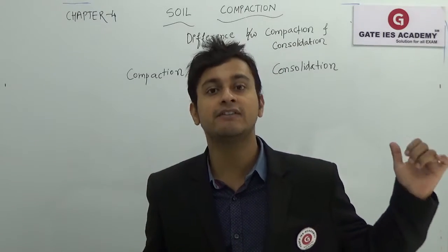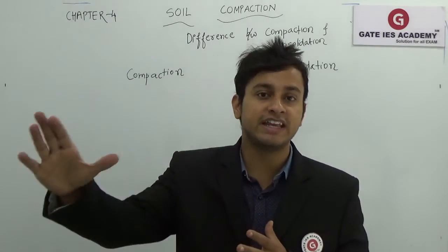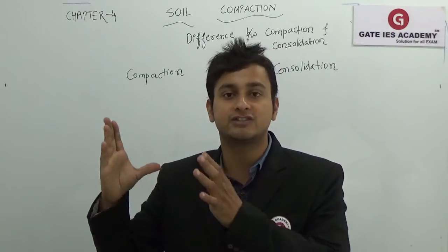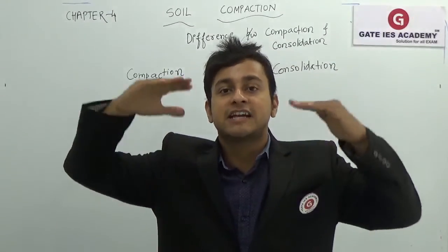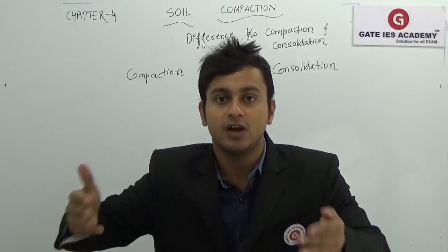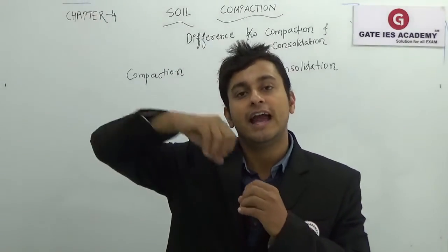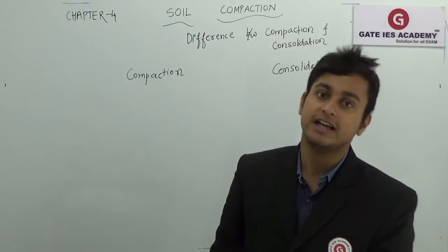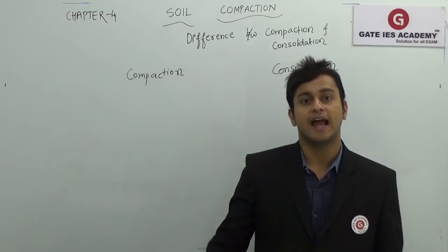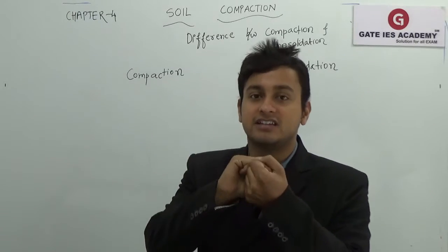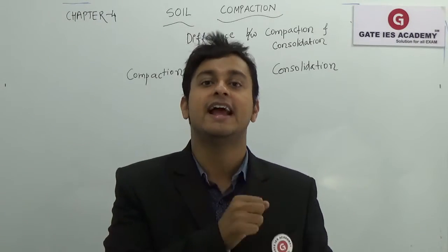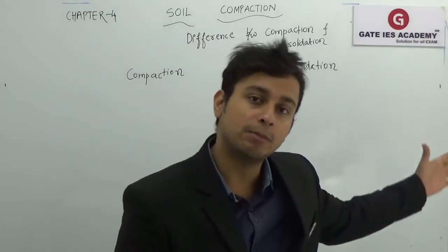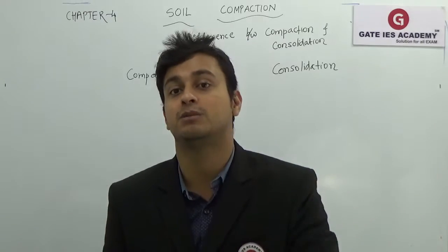Here in compaction we have unsaturated soil. So we don't have any air voids in consolidation. It is a fully saturated soil, and under direct loading which is kept for a long duration of time, the water expels out of the system. That is nothing but the excess pore water pressure that is coming out of the system, and therefore the soil grains come closer to each other and consolidation is achieved. This is a time dependent phenomenon, and compaction is an instantaneous phenomenon.